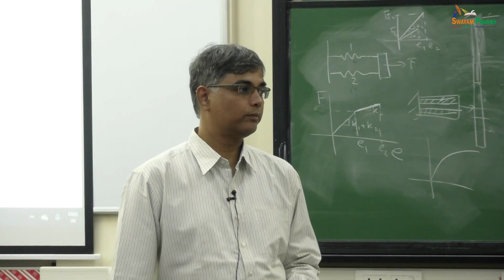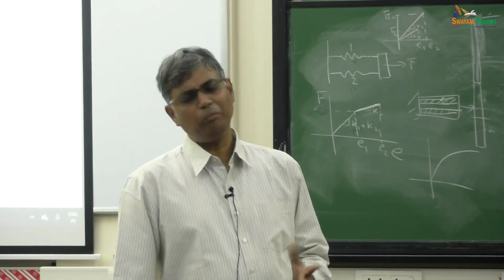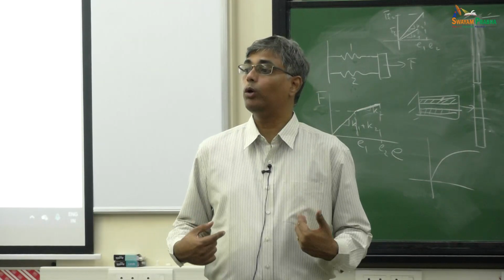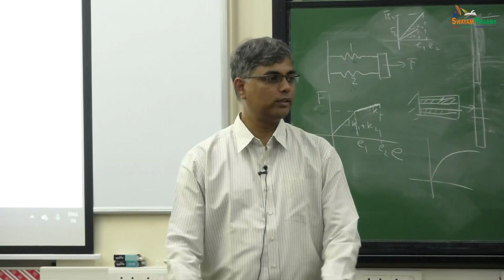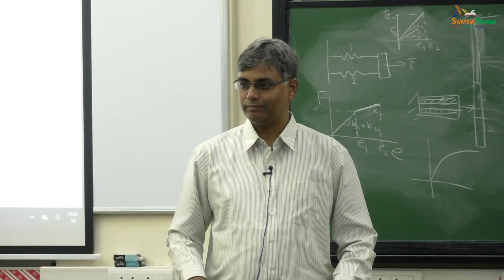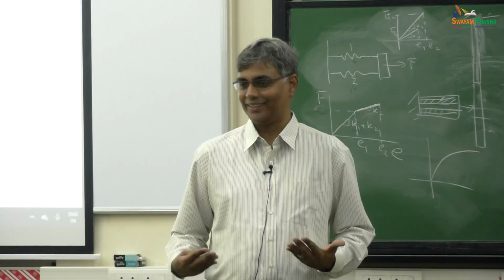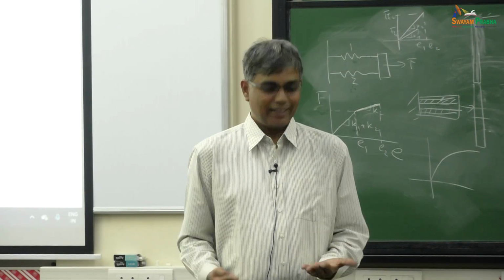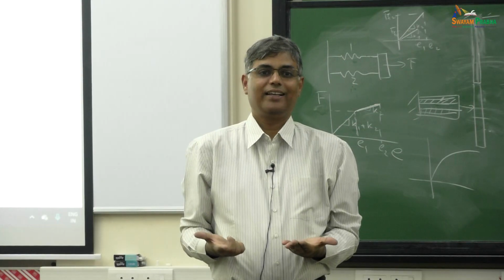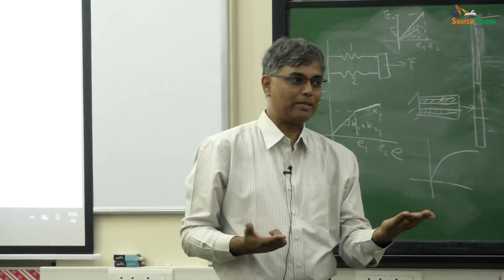Yes, sir. But which will be more common generally? See, I would say both are equally likely. For example, if I want to model how the floor is in relation to me, I am applying a force on the floor. If I want to model my body, I will apply displacement control because the floor is so much more rigid than me. It is just going to support me. Even if somebody comes and sits on my head, that floor is going to be at the same location. So displacement is known. Those are all displacement control situations.